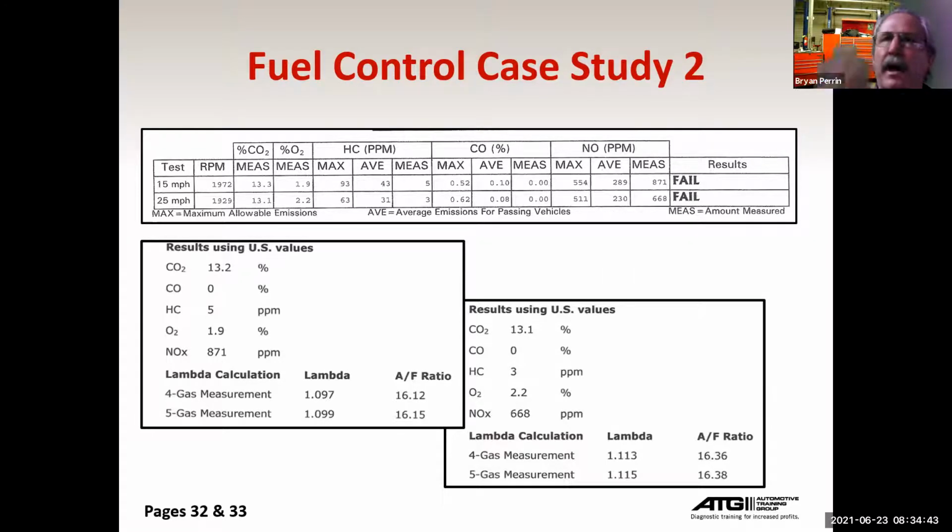Maybe it wants to be at operating temperature. Maybe it wants some of those things. So I checked, yeah, the car's at operating temperature. Again, I'm looking for that low hanging fruit. The car's hot. The electric fan's coming on for the radiators, blowing hot air. I have an O2 sensor that I already know is good. I tested it. It can use propane. I can see rich. I can see lean. So I know it's correctly telling the computer.